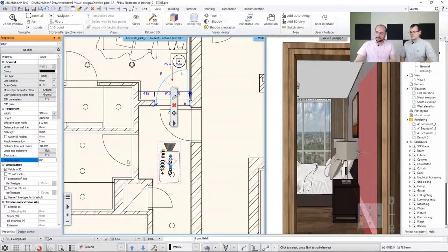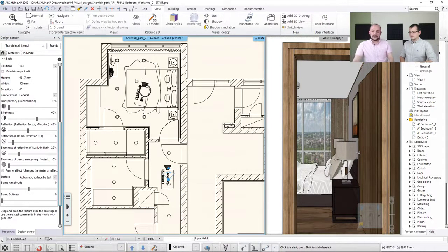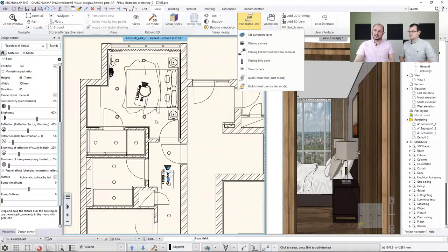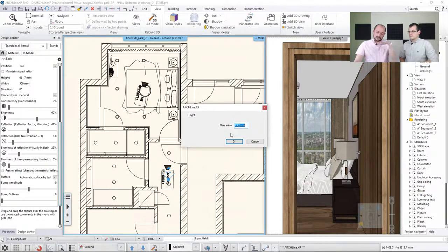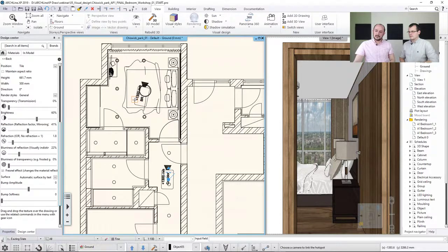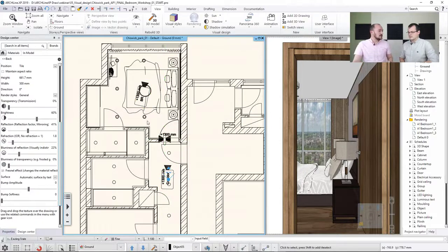So now it's open. And then there is one other thing that I should do, and that is to connect those cameras. So when I do the Panoramic 360, I can tell the software that I'm actually traveling from this camera to this one through this door. So that's the link hotspot. For that, I set up the height, and I set up the first camera, the second camera, and its location in the 3D space, and I can just keep going. Now I already have these two, so I can actually generate the visual.